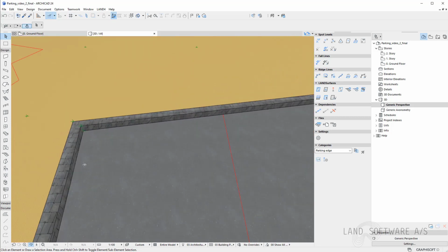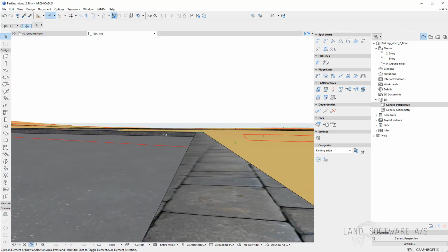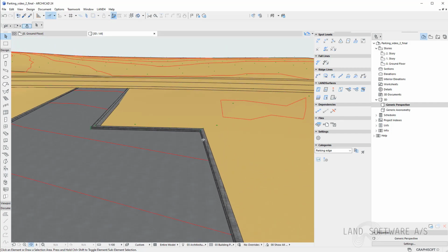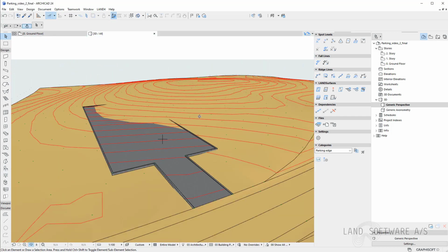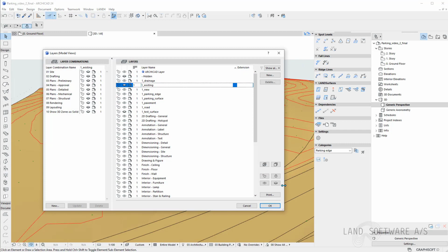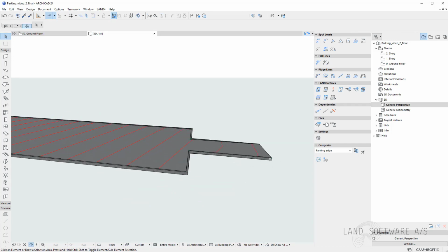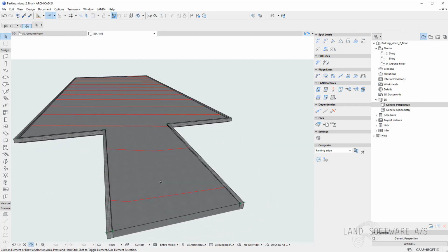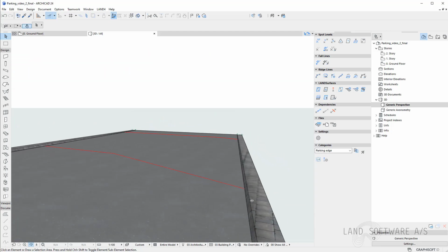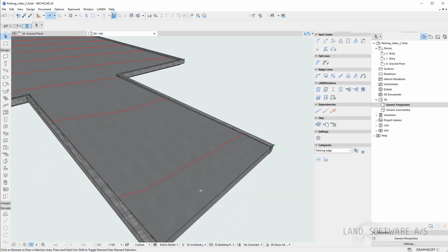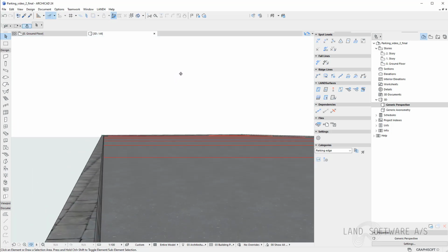And here we can see now that our surface is following and meeting the parking surface. I can also hide the existing terrain so I can have a better overview of my construction site. And close to the road, we can see that the parking edge is basically meeting the parking surface in level, while all around, we have a 10 centimeters in difference.